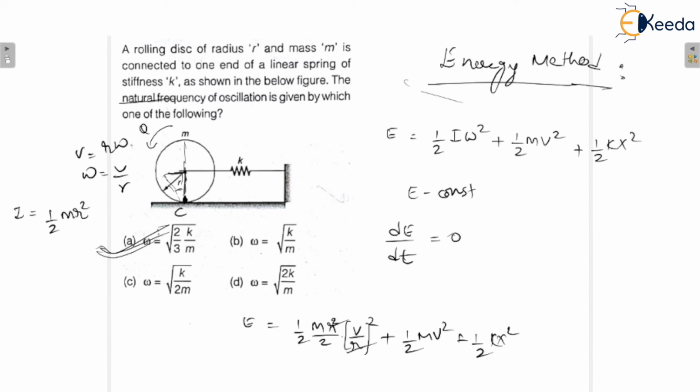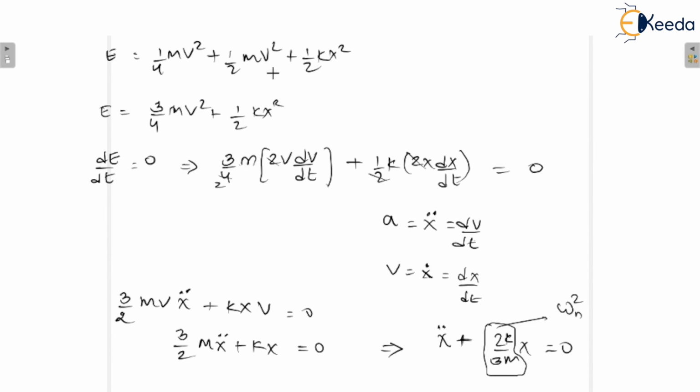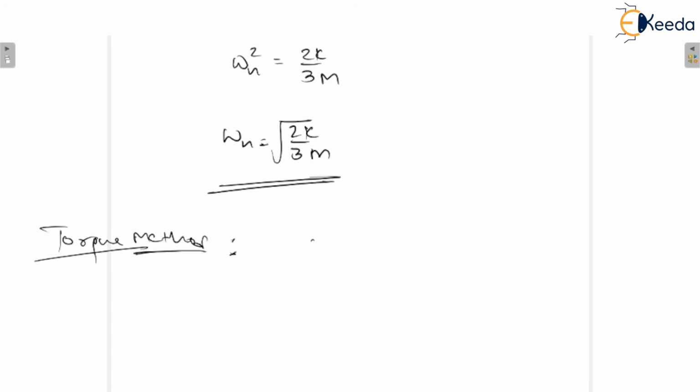Okay, so the spring will have a displacement in the horizontal direction, so it would be the displacement of the spring. So this is nothing but r theta. Okay, this is the displacement r theta of the spring. Okay, so if you want to write down the equation, it would be I theta double dot plus k r theta, and we are considering torque, so it would be multiplied with r is equal to 0. So you can see here that I theta double dot plus k r square theta is equal to 0.